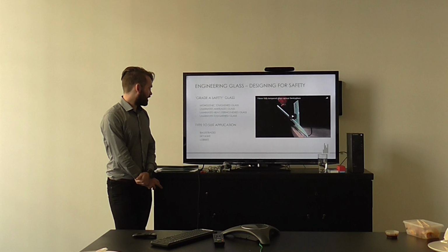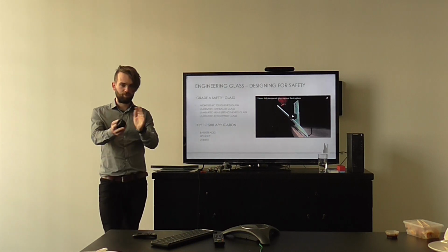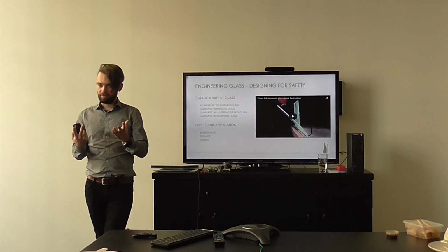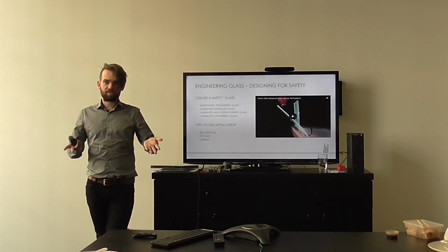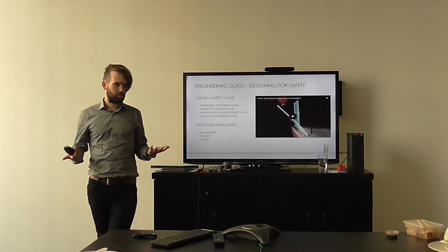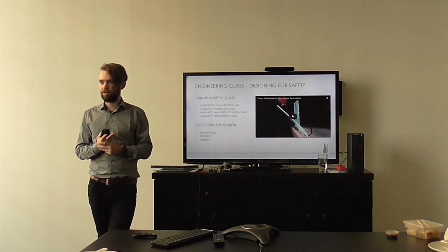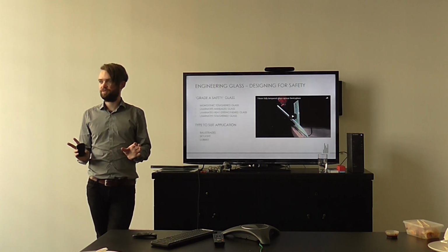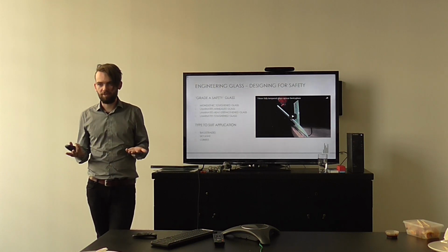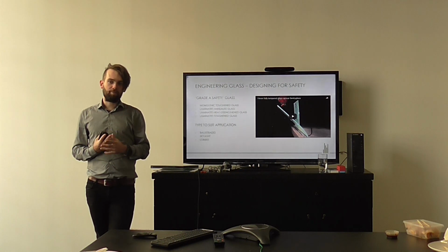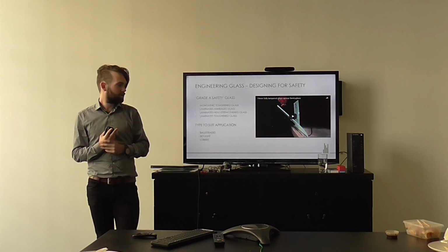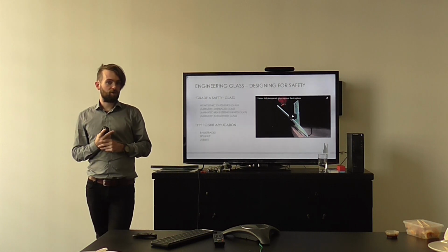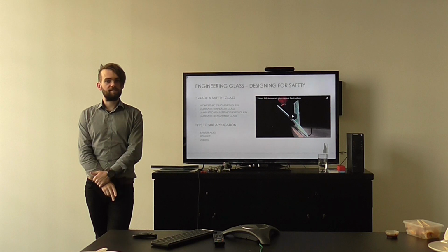Yes. So going back a little bit, when we put glass into our framing, most applications put it on what are called setting blocks, which some of you may or may not be familiar with. Essentially they're small hard rubber blocks which sit within the frame and stop the glass sitting on the metal, which is not what we want. But there can be some tricks with this. There's good literature on it in AS 1288, which is quite clear on what the requirements need to be.